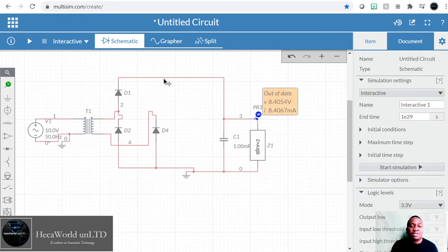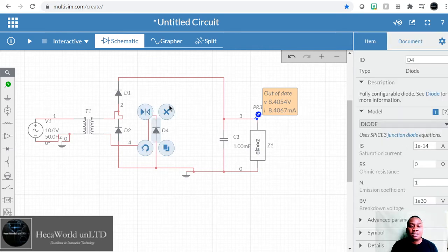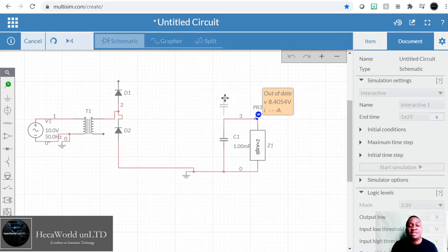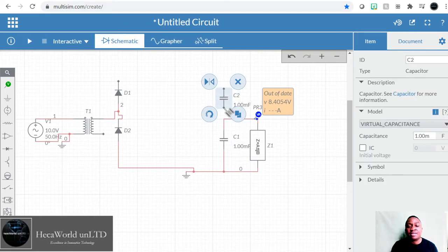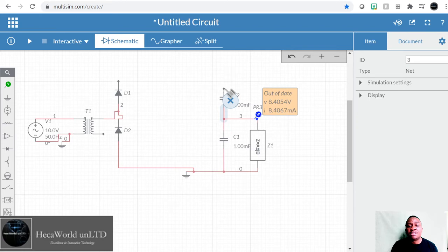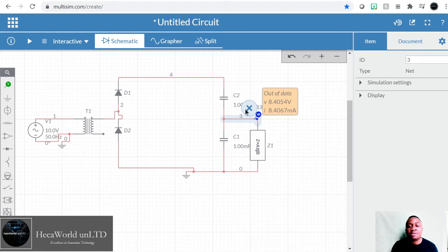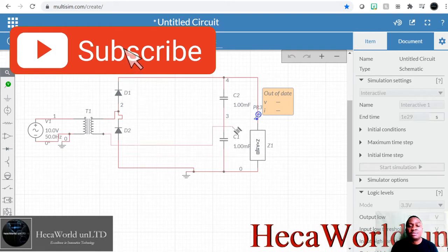So to do this step up, we can use a voltage doubler. Let's do a voltage doubler. We still have 10 volts here. Let's see what we're going to see in the output when we do this voltage doubler. And to do a voltage doubler, the quickest one I used when I built amplifiers is to use 2 diodes and 2 capacitors, right? So this piece then will go to the top here, and then this piece will go to the middle here.